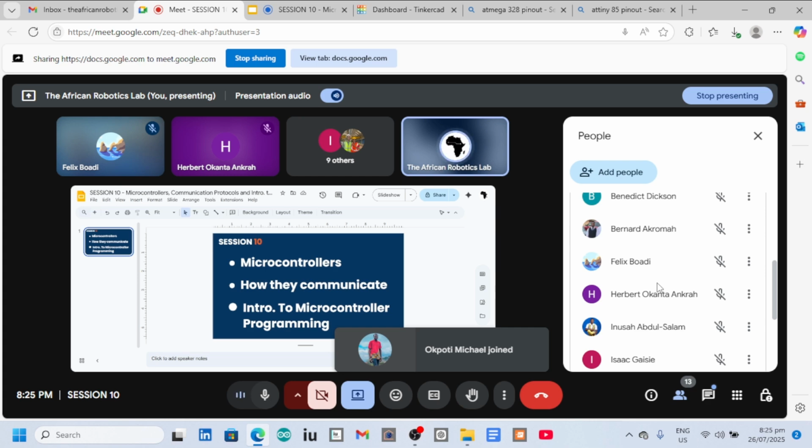And so what we want to do is, let's say your microcontroller requires 5 volts to work, or your LED requires 5 volts. Your LED may require 3.3 volts to work. And so what you do is you use a voltage regulator. There are some voltage regulators that are rated 5 volts, right? And they will tell you that the input of this voltage regulator can take a huge battery of, let's say, 7 volts to 12 volts, and it's going to step that voltage down to a desired voltage, right?